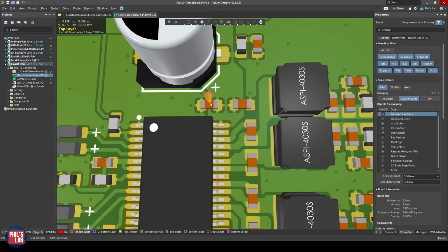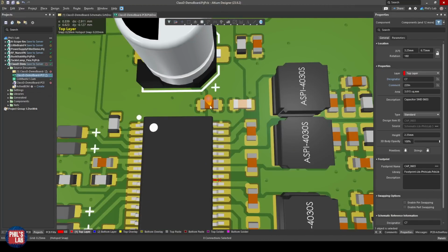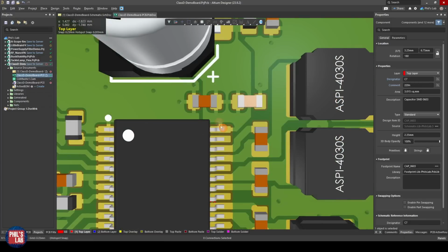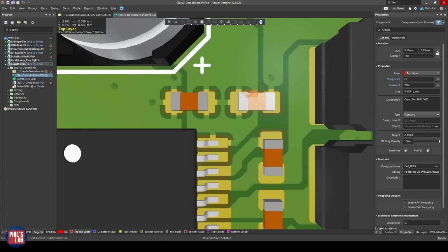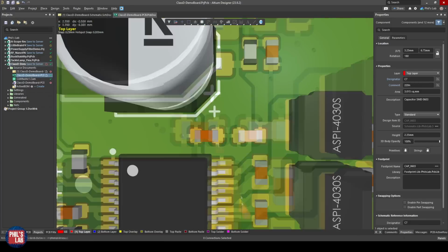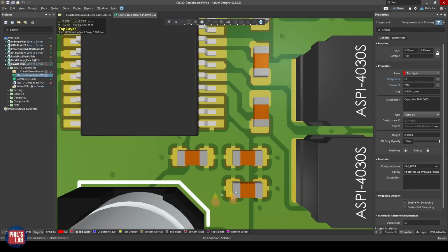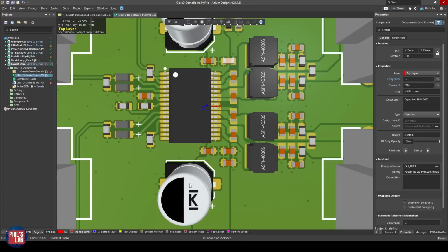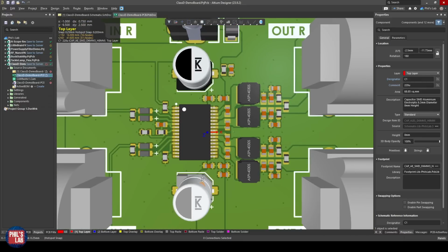What's important is for these bypass and decoupling capacitors, the ceramic capacitors, these small packaged ones, to be close to the IC power pins. For example, the power pin at the top, we have our bypass and decoupling capacitors very close. Same thing for the bottom side, bypass and decoupling capacitors very close. And further away we can place these larger bulk bypass capacitors, these aluminium electrolytics.